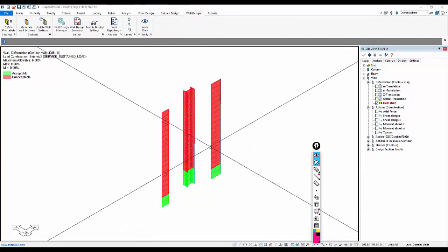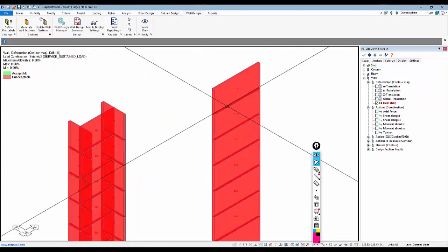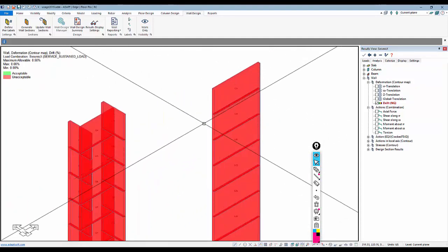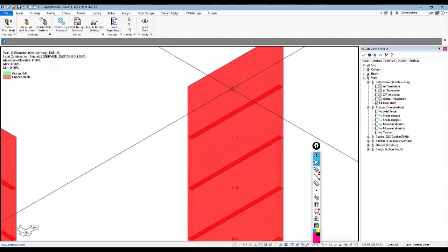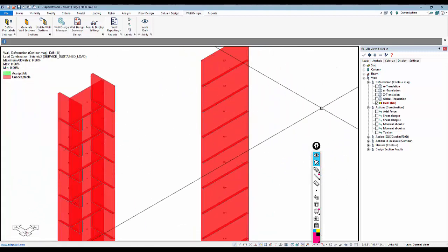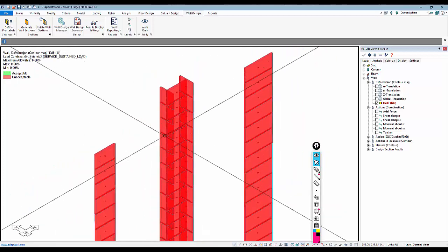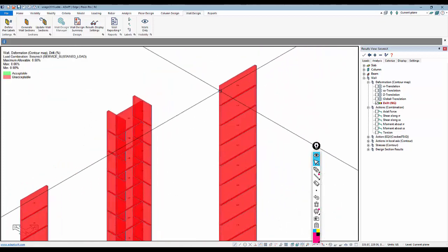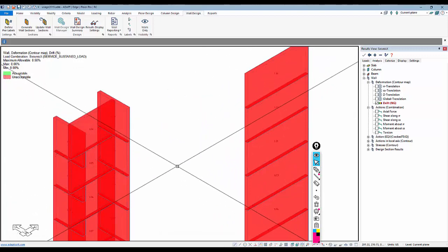So this result would then allow you to evaluate drift, and we kind of frame that as a reason why you may want to evaluate the system under different assumed cracking modifiers or stiffness modifiers. And you can see here just some of the drift percentages of each of the different wall levels. So this gives some output in terms of drift for these particular walls that were used as a primary lateral system. Now for example, if we look at these two top walls, this is 1.16, 1.04.